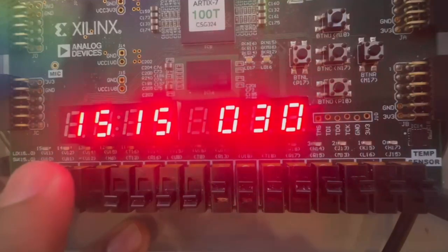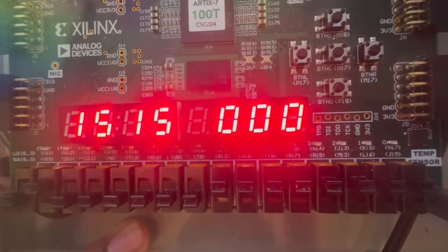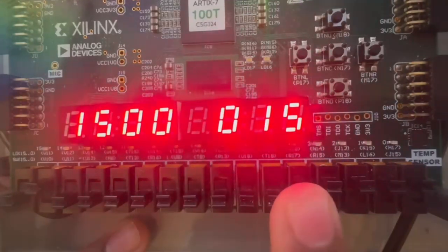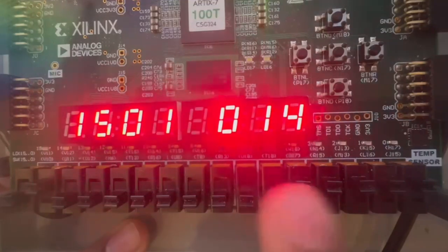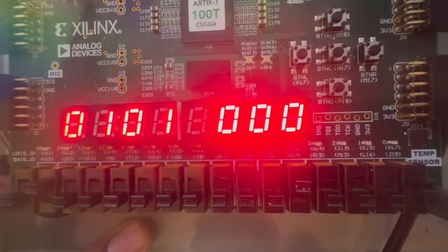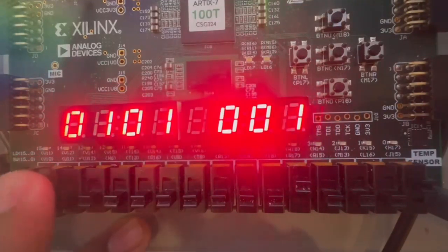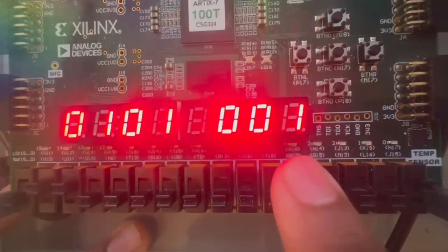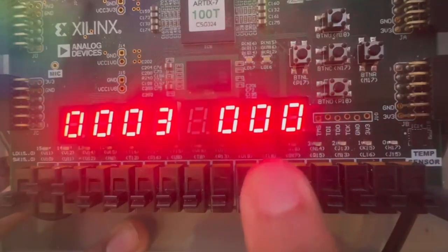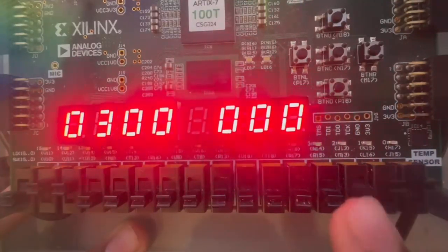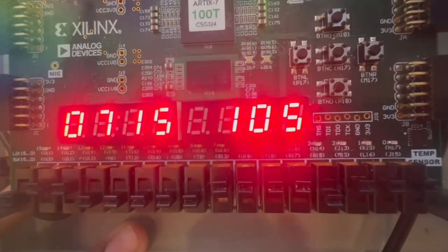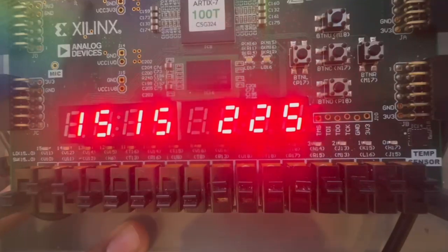Next, you can see we'll switch to subtraction on the left side to mode 010. And you can see how the result is immediately updated to reflect the new operation. Next, we'll move to multiplication with mode 011. And you can see it can handle all different inputs, including multiply by 0 and a max of 15 times 15, resulting in 225, and everything updating immediately.